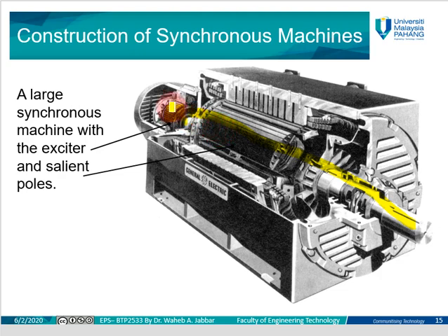The exciter gets AC power, converts it to DC to the stator winding. Then in the rotor winding it will induce a voltage which is AC. It also has a rectifier that converts it to DC, then it goes to the rotor inside this part of the machine to produce the field DC current, which will produce the magnetic flux and induce the voltage in the stator part.